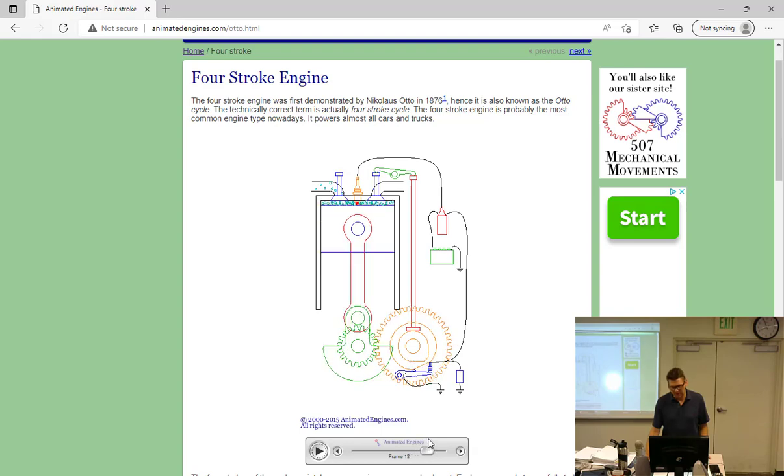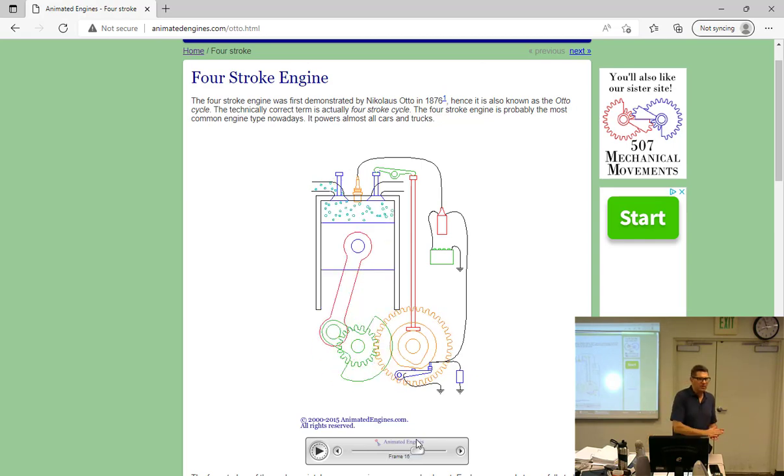This ignition happens late. Now, the nice thing about this is when you're starting an engine, that's what it's got to look like. You have to fire it at top dead center, because if I fired it, oops, piston's coming up. If I fired it right there, the piston's coming up under the starter, bam, it'll push it right back the other way, and it'll blow teeth out. The starter teeth will go out, and Continentals, they have a big spring inside of the engine that winds up around a drum. It'll launch that spring into the inside of the engine. The only way to get it out is to take the whole engine apart and overhaul it.